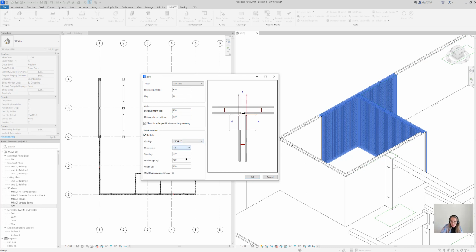And what you can do is insert a reinforcement going all the way through the connection. And take a look at the dynamic picture again. It just shows you your settings. So in this case, I'm gonna just change the anchorage and the width.